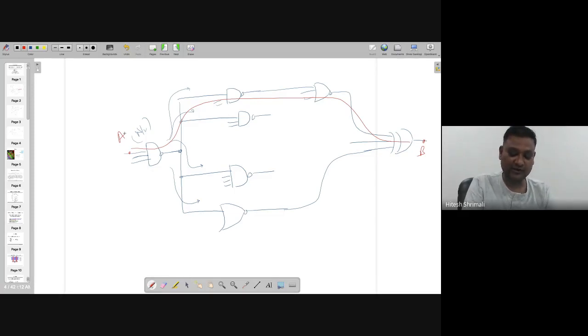It will also give the correct answer. The only thing is that all of them have to be looked at in terms of RC, and you have to make the equivalent model, and then you can find these things. For one particular gate, that's fine, you can do that. But for a number of stages, you need to devise a technique that gives you the accurate answer with less of the hand calculation required for the RC or the Elmore delay.